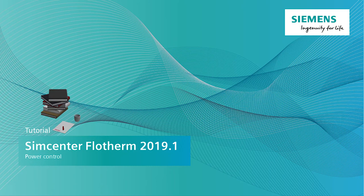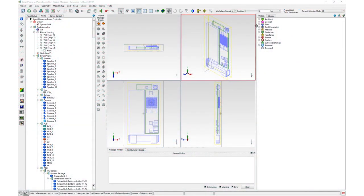Welcome to this video where I'll be showing you how to use the power control functionality in Simcenter Flotherm 2019.1. This feature, consisting of a new controller object and control attribute, allows frequency-based power control based on the temperature of a monitor point. To start, create a new control attribute.